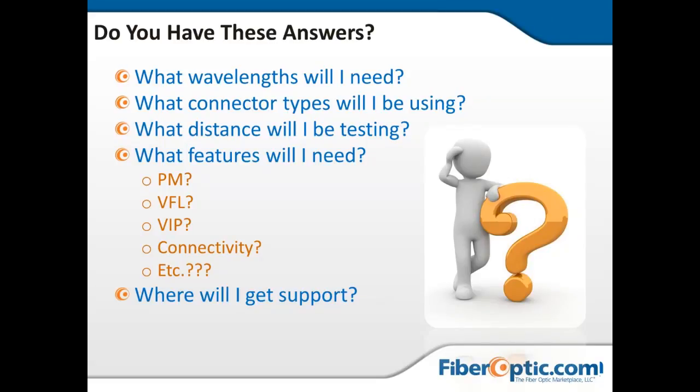training the technicians in the field on, was: what is the first step that you would take in troubleshooting a fiber if you went out into the field? And I believe what we understood the first step would be was that they would use a power meter to see if power was coming through the line. So normally this could be a separate unit, but if you want to keep it all in one, it makes some sense. So the first step would be to unconnect the fiber from the port, plug it into the power meter, get a measurement to see if any kind of light was coming through.